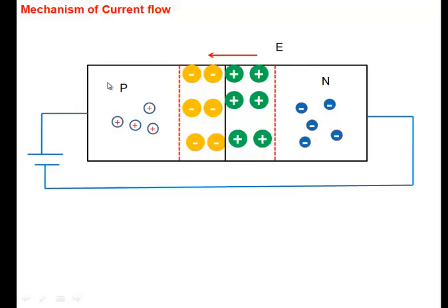The hole has gone over and recombined with electrons, and because you create a charge imbalance, a hole gets injected from the contact. So it replenishes the hole that was lost from here. This electron that you see here goes like this and comes over here and replenishes the electron that was lost due to recombination. Okay, so that's how the current flows.